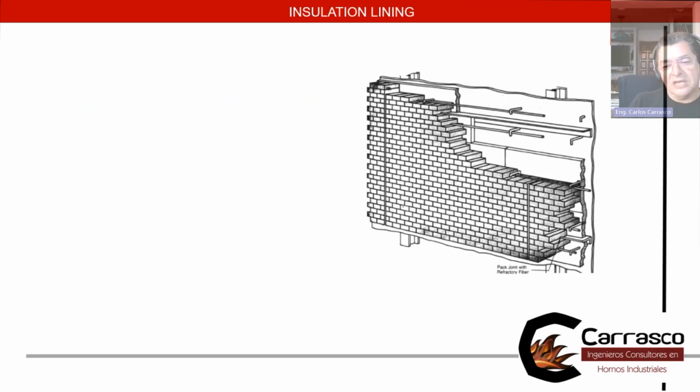Okay. There are different ways to isolate the furnace from the heat, either to use bricks, or back it up by a board, let's say, that can stand less temperature. Most of the time we use a combination of bricks that can stand either high temperature or mechanical abuse, because sometimes the load can hit the walls, or those high speed burners that I was showing you are very aggressive to the surface, very abrasive to the surface.